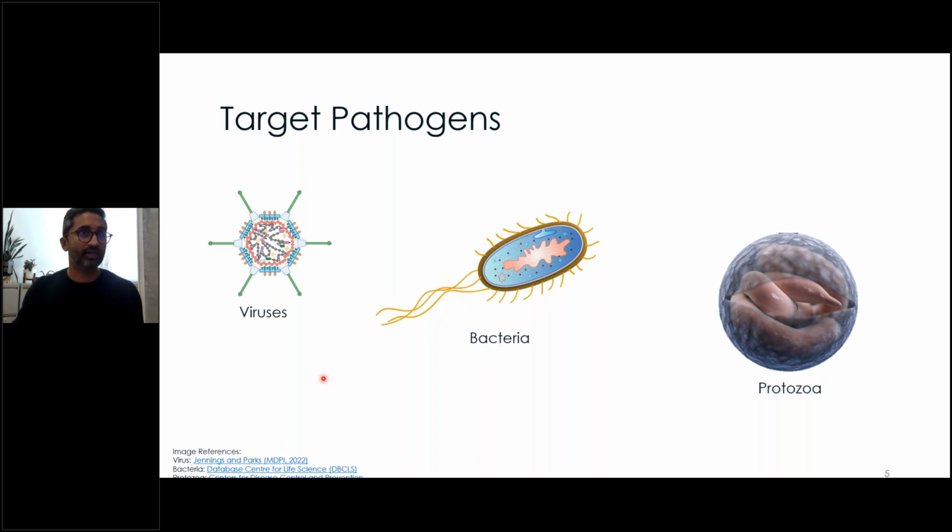And the way that chlorine, in this case, works in treating these pathogens is almost the same. It enters through the cell wall, it penetrates this outer shell that exists for each of these, and it attacks what's going on inside. And by attacks, what I mean is that it starts reacting with the proteins, the DNA that exists within these microorganisms. It starts oxidizing them, reacting with them, and basically rendering them ineffective. And when they become ineffective, it means that these microorganisms can't infect you if they're consumed, or they also can't replicate if it's affecting the DNA.